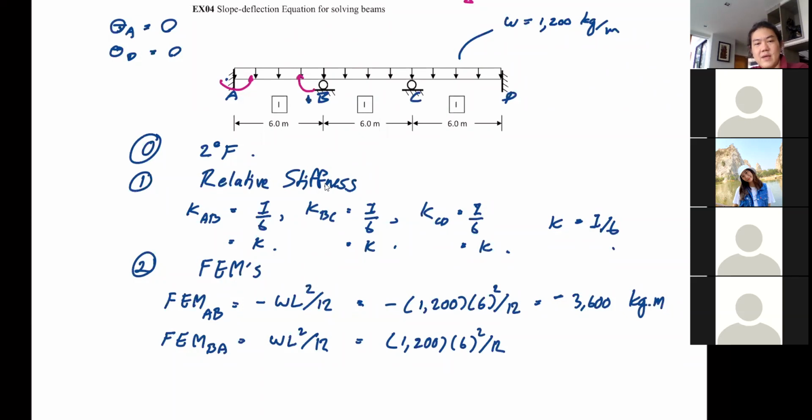And you have to say that the calculation of fixed end moment will reflect the load that your structure has on it. So failure to calculate fixed end moment, which is relatively easy, will mean that you are analyzing the structure with not the same loading condition. I have to say that. So if you get the fixed end moment wrong, the rest will become garbage.